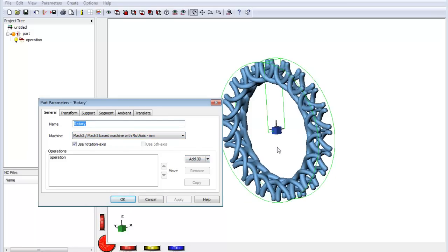Right. So at the moment it will find the smallest, narrowest margin it can around there. So it's going to try and bring the cutter down if it can, possibly all the way down to here. The way that we're going to cut this is not going to matter because it's not going to go over the edge of the outside. But if the cutter can see through the middle, it will try to go down. So we're going to set a Z bottom to this.